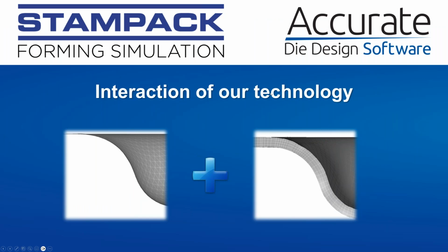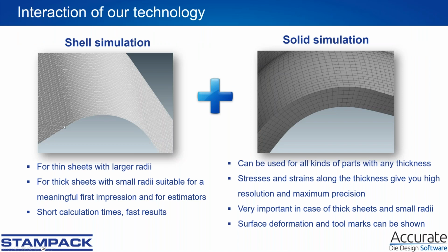So now you have a feeling for what Stampack is doing, and now I would like to come back to the aspect of fast result and reliable result. And we will speak more about our technology, that is here the shell simulation and the solid simulation. So with shell simulation, I mean the blank here is in the mid surface of the sheet, and it's a two-dimensional surface, covered by triangular elements. And this technology is very good because it's extremely fast. So no matter how big the part is, you can make a simulation in 5 minutes, 10 minutes, 15 minutes.